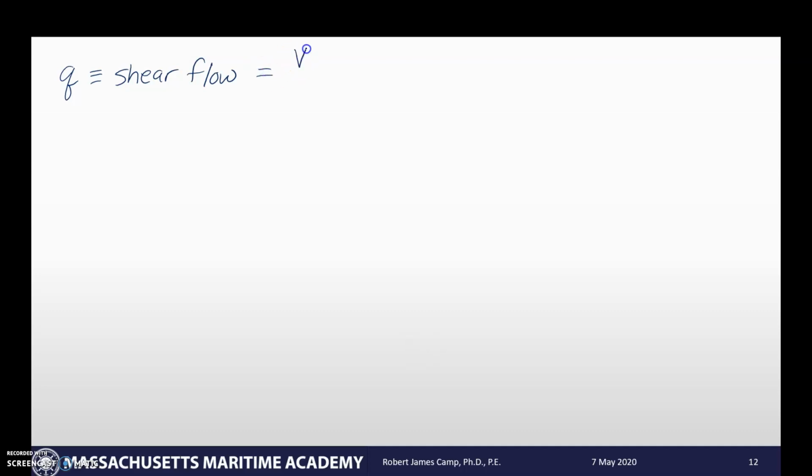So we're going to look at, once again, the vertical shear force V that's being seen by the beam at that time. We're going to divide that by the moment of inertia of the area, I. And then we've also got Q again. And so remember from the other ones, what is Q? Q is going to be y bar prime times A prime.